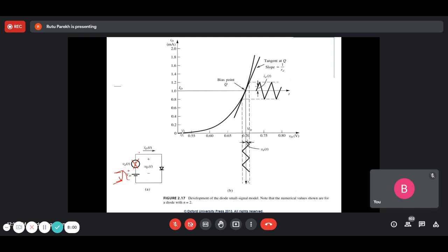In that case, if you want to make this a full wave rectifier, we have to rectify it. This is 0, let's say. You want to rectify, then this 0.7 drop is not a big deal, right? We can neglect that. What you get at the output is the rectified signal. If it is full wave, you will get this kind. This will still be 0 and this will be 100, or to be more precise 0.7 less than 100, but it is almost 100. So that is fine in that application.